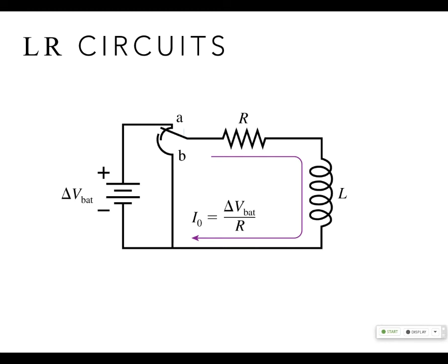So if you have music signals coming in, frequencies for TV sound or music, and you have a surround sound system, you might want to filter the high and low frequencies and send them to different places. So that's a really good way to use an RC circuit in AC. Instead of in DC, it's just a decay, right? But in AC, one side's going to send the high frequencies out, the other side's going to send the low frequencies out. So it does have some good applications.